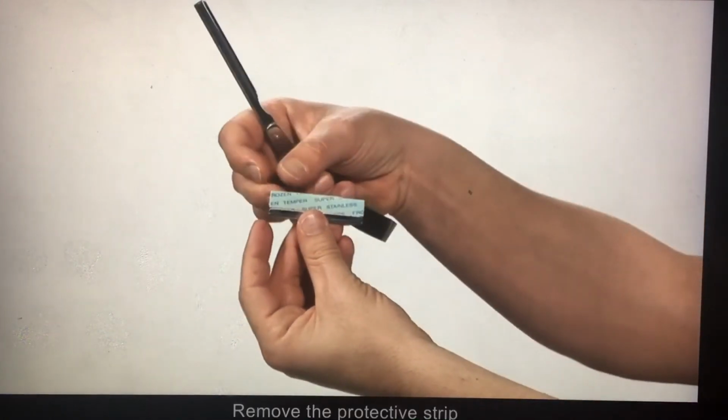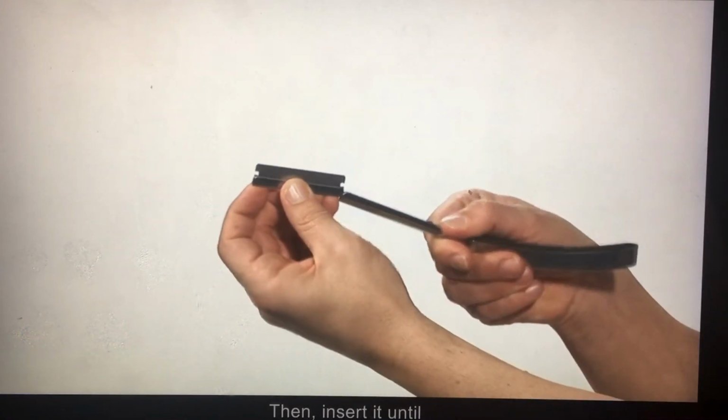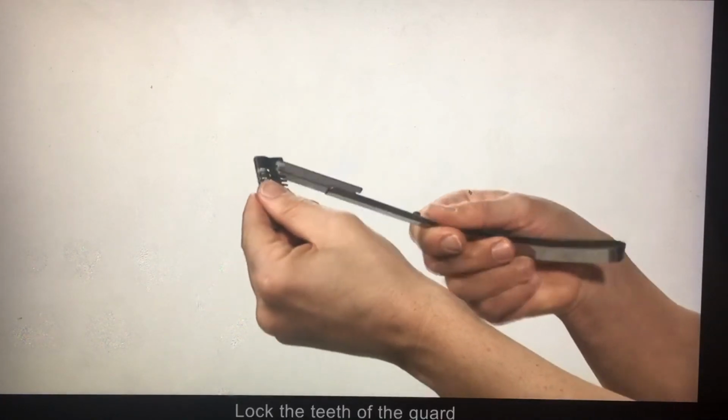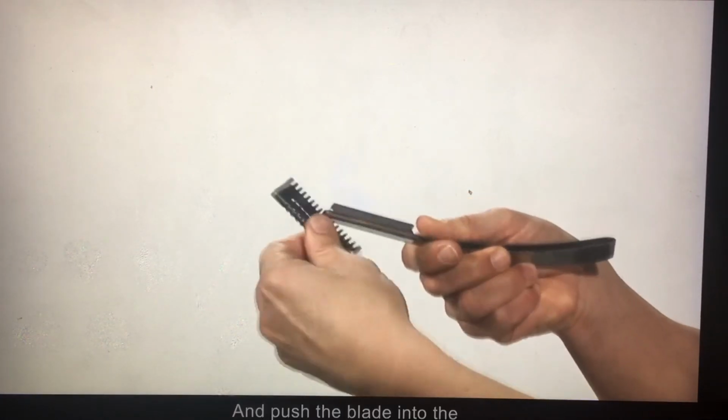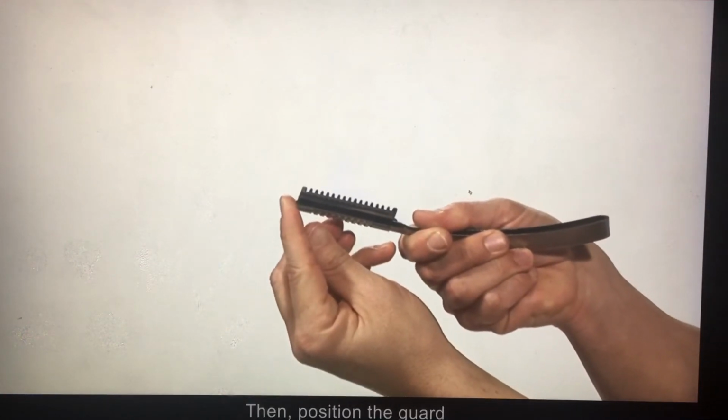Remove the protective strip from the new blade. Align the blade with a blade slot, then insert it until it is secure. Lock the teeth of the guard into the blade and push the blade into the full slot position. Then, position the guard over the blade.